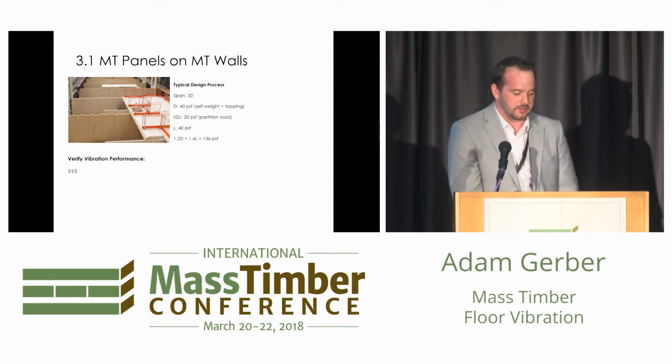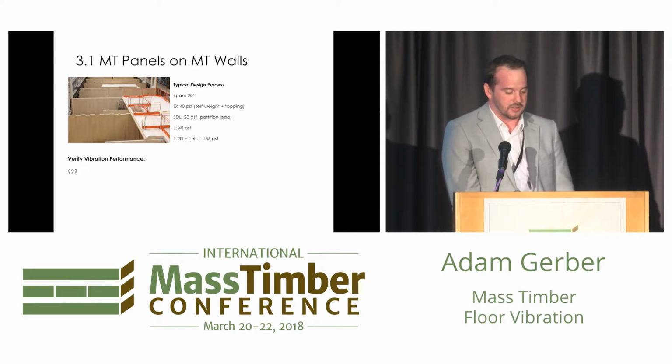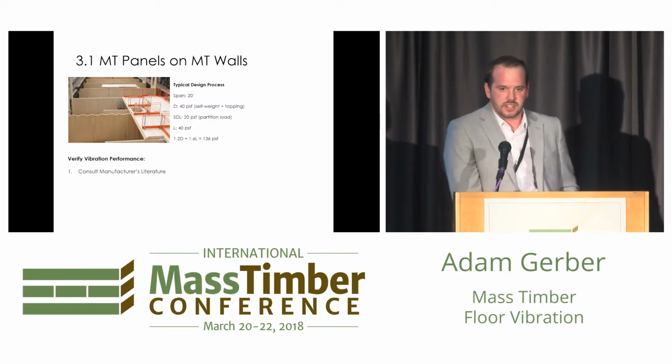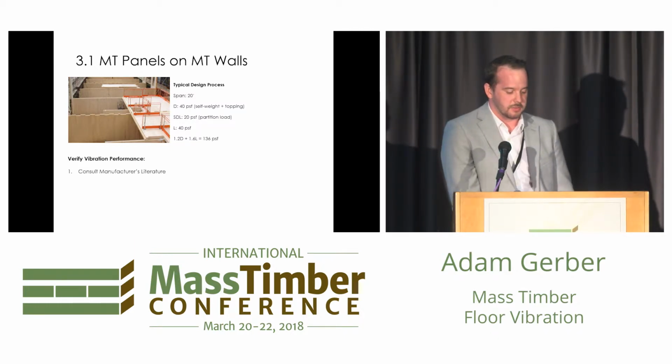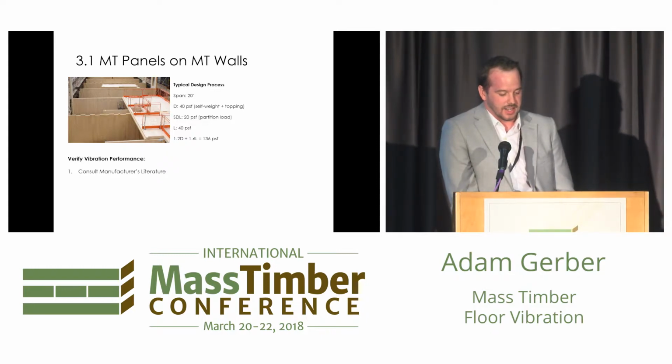And so now we're through the typical phases of design, and the question is asked: what do you do about vibration? How do you assess whether or not it has adequate vibration performance? The first thing typically to do is to consult the manufacturer's literature, and at the end of the day, the manufacturers have installed far more projects than any one designer in all likelihood. And so they've heard the feedback from the clients, they've experienced these issues in the field, and they generally have a good idea of how to deal with them in design.